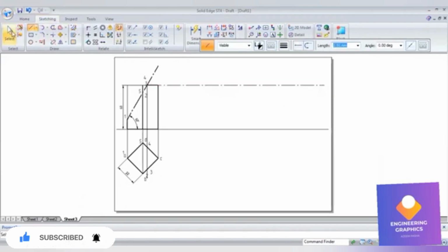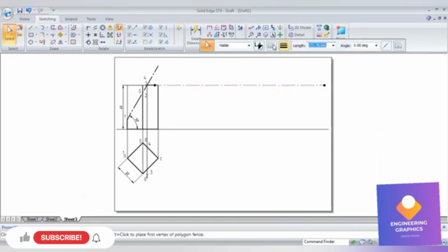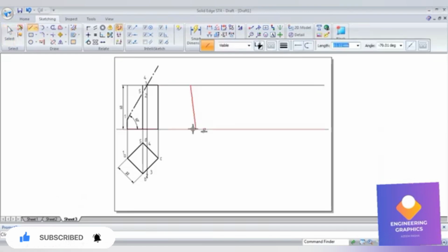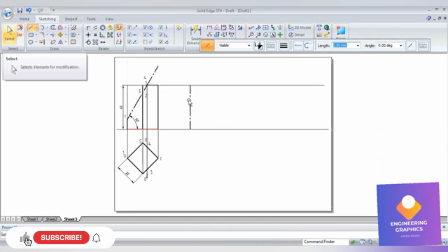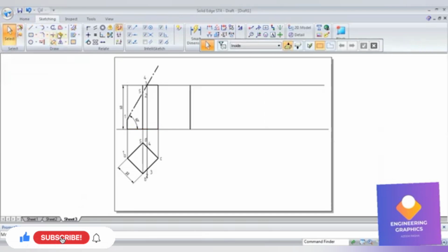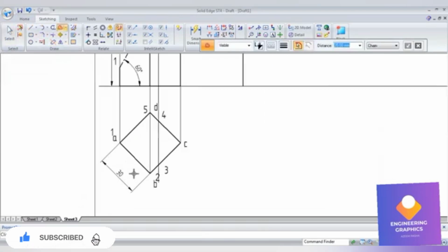Now we have to do the development. Draw the projection lines from here, and draw the continuous line here. Now we take the vertical edge, because this is the parallel line method, as it is a prism. So draw a vertical line. Anywhere you can take a straight vertical line.